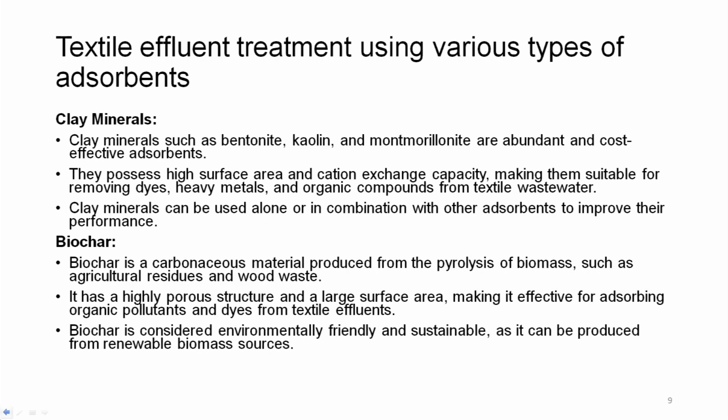Clay mineral, this we had learnt a little while ago, but we will again look at it. Clay minerals such as bentonite, kaolin, montmorillonite are abundant and cost effective adsorbents. They possess high surface area and cation exchange capacity, making them suitable for removing dyes, heavy metals and organic compounds from textile effluent.